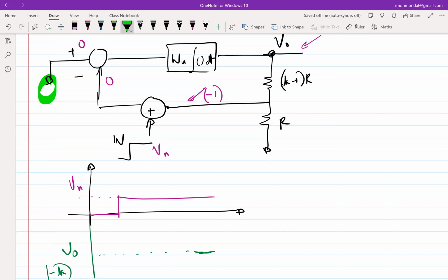Adding an input there is equivalent to adding an input here, but with a negative sign. So it's equivalent to saying that I have applied an input of -1 volt at the traditional place. So the output has to be minus K. That's true, but the answer I'm actually looking for is that you have changed something in the sensing path. Go back to the scenario of driving. If your speedometer is broken, you will take a wrong decision.